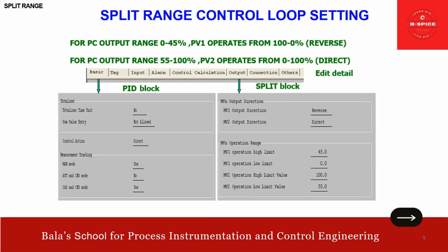The controller calculates how much the MV needs to change, meaning in our case how much the valve needs to open or close, based on the difference between the PV and the set point. I hope this is clear. So again, PV is the process variable we measure and MV is the variable we manipulate to control the process.